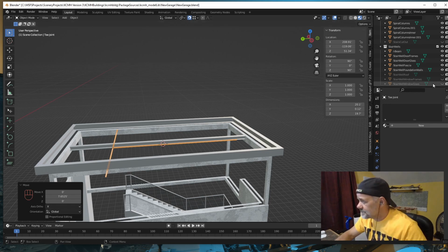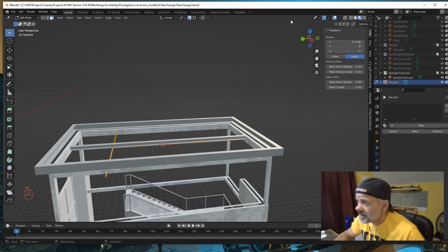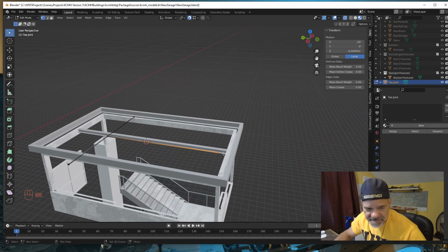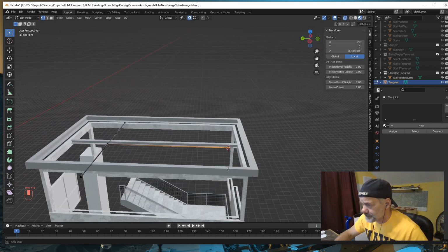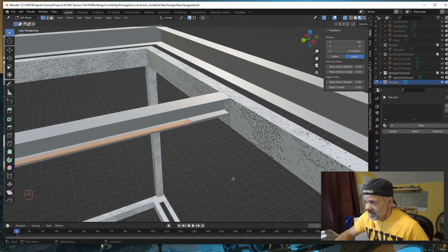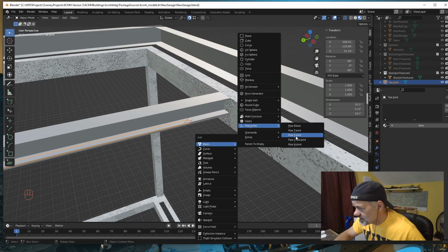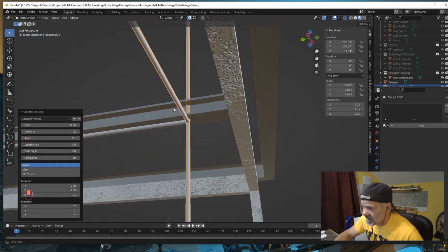I'm going to add, it's not put into my collection, but that's okay, we can move it later. So what we're going to do is go into edit mode, ghost, vertices, select all our vertices, they're all selected, yeah, and I'm going to Shift S, move our cursor down there. All right, and then I'm going to hit period, kind of focus in that area. Now get out of edit mode, Shift A, and Mesh, Pipe Joint, T. So it adds another T joint there.